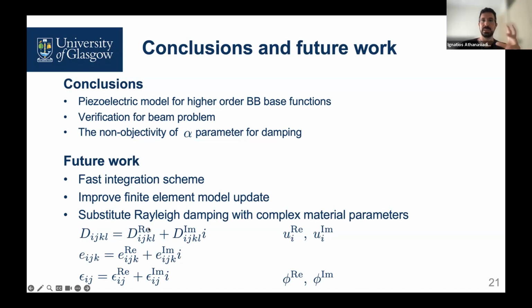And this is something that is relatively natural for MOFEM, as a lot of the effort that has been done for the development of its architecture is to be easy to work with many fields. And when we are going into the complex coefficients, we essentially go into complex fields that you can see on the right. And this means that from a two-field multi-physics problem, we go to a four-field multi-physics problem. And this is quite natural for MOFEM.